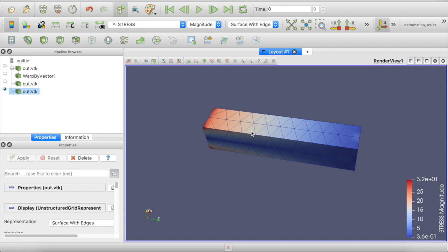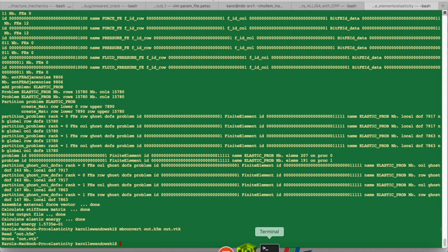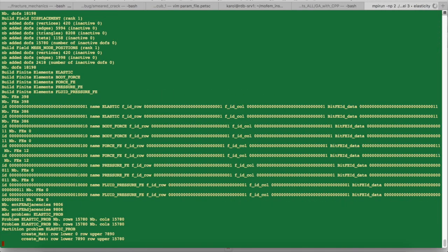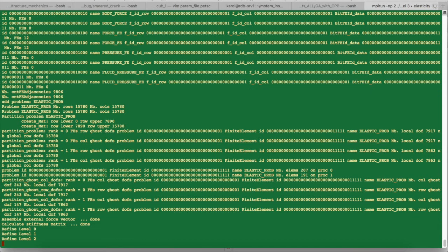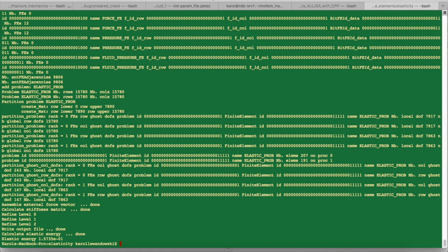one tetrahedron. But what we can do is to use a MoFEM feature called post-processing refinement. So we can use the parameter my_max_post_proc_ref_level, for instance 3. So what it will do is divide our mesh in a way that we can observe the increasing order of approximation.